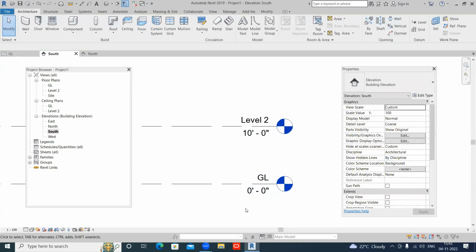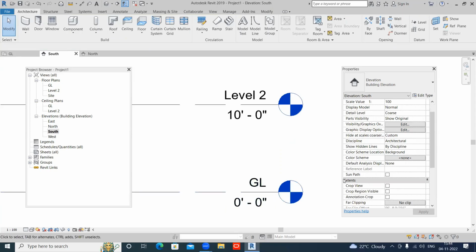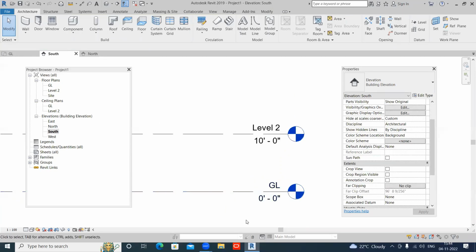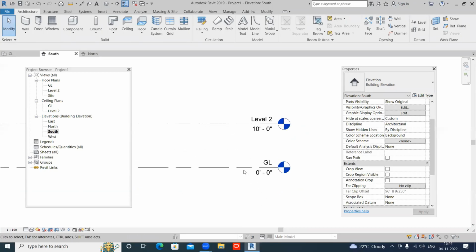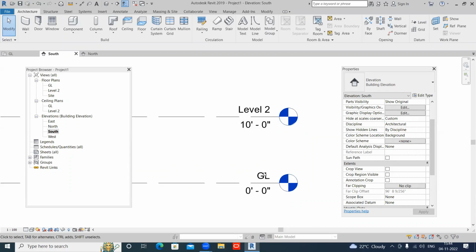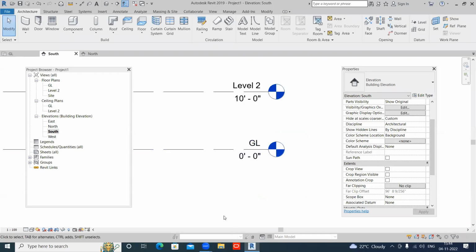Usually when we do construction, we will construct at plinth level, right? So this can be considered as finished floor level also, or your starting point of the floor. Below this, we will get our ground surface and everything. Mostly for foundation, we have to show below this, so the depth of the footing, how much you have to mention it below.